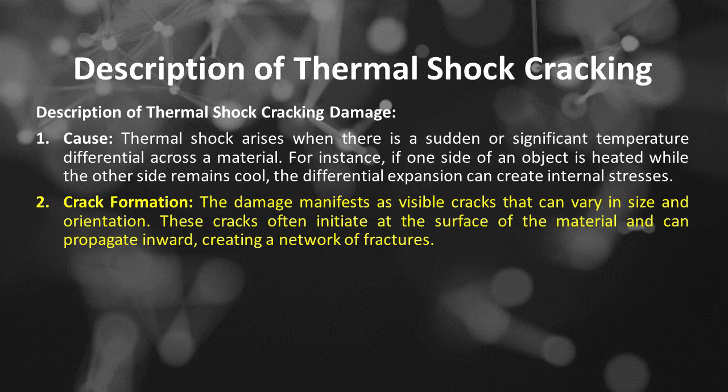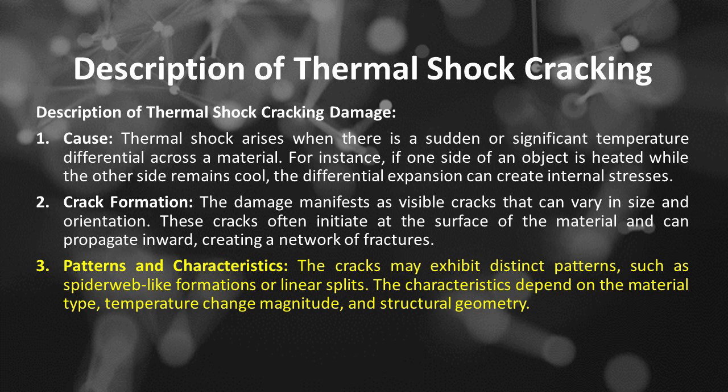Number 2 is from crack formation of thermal shock point of view. The damage manifests as visible cracks that can vary in size and orientation. These cracks often initiate at the surface of the material and can propagate inward, creating a network of fractures. Number 3 is from patterns and characteristics of thermal shock point of view. The cracks may exhibit distinct patterns, such as spiderweb-like formations or linear splits. The characteristics depend on the material type, temperature change magnitude, and structural geometry.